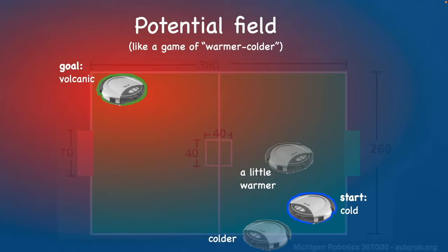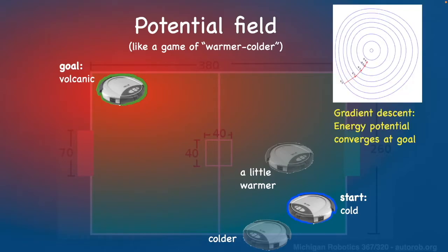And so the technical approach for implementing this type of motion, once a potential field has been constructed, is using an algorithm referred to as gradient descent. The idea with gradient descent is that if you define a potential field, you can move according to that potential field such that you will maximize your potential at the final configuration.